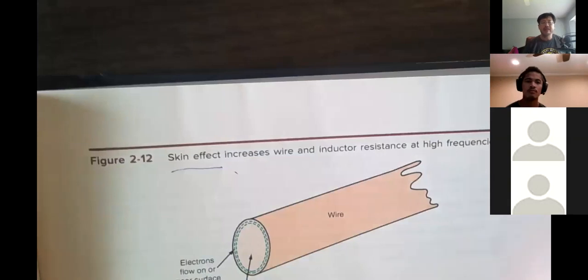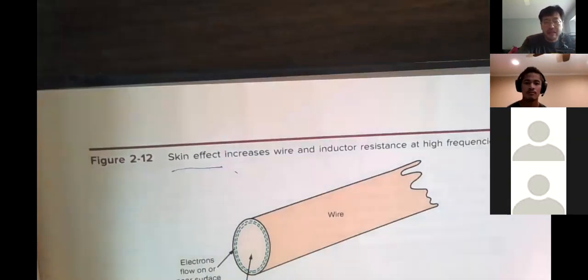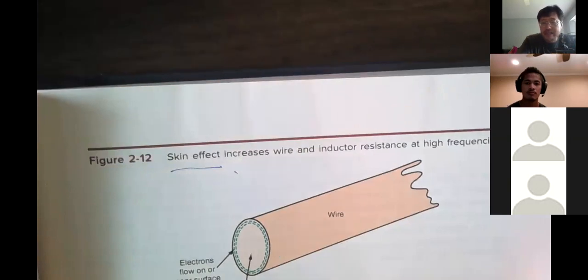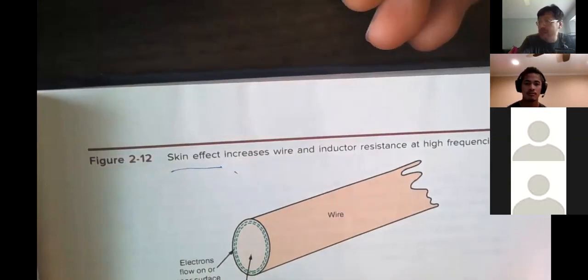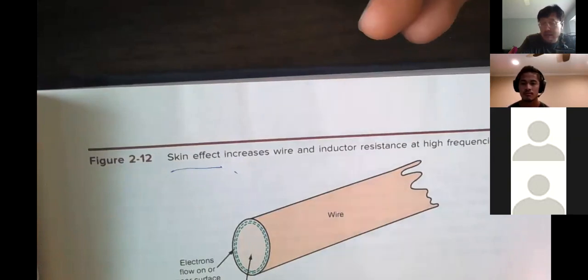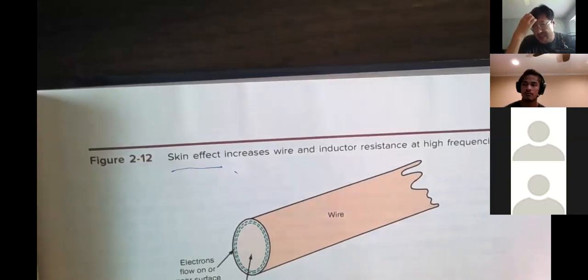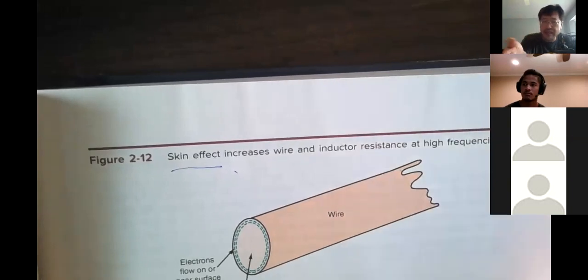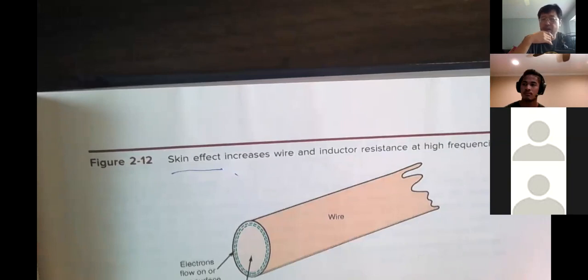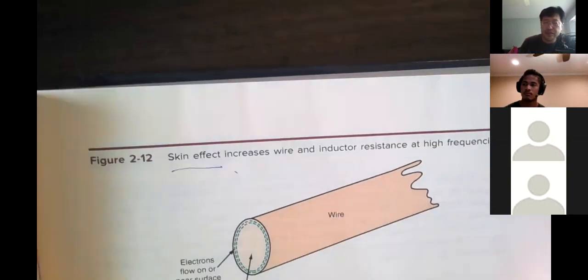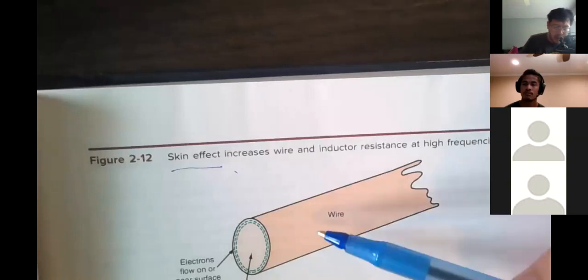But typically, if you think about a conductor, for example, wire gauges. If you wire up to an ordinary outlet, you use small gauge wires, right? When you wire it to an oven or a heater or dryers, you use big wires. Why the big wire? Because the big wire has more cross-section area. That's more important. But unfortunately, that is not true for RF.